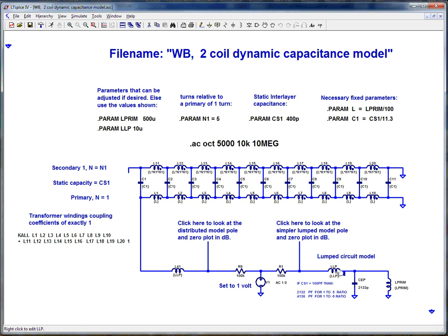We have one inductor, meaning the leakage inductance, another inductor, which is the magnetizing inductance. Here we call it L primary. Sometimes those words are interchanged. You can call it L primary most of the time because this leakage inductance is just a small part of it. It's only a fraction of its value in a real transformer, unless you deliberately design the leakage inductance into it to be a large value. It normally is a small one. But what we're doing today is trying to find this value.